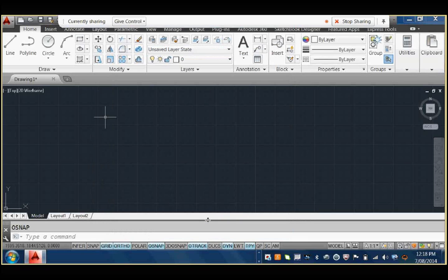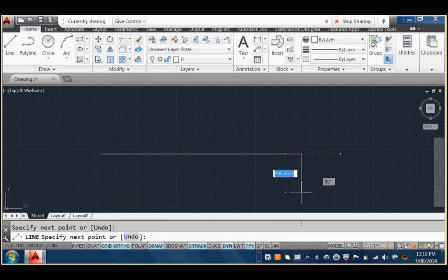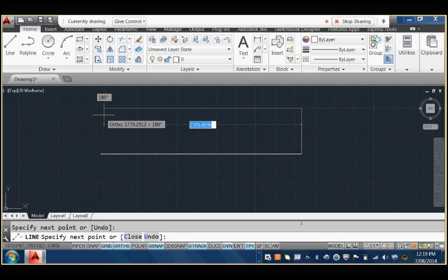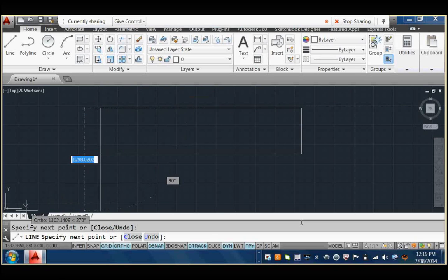Essentially, AutoCAD is command-based, and you can click on the icons here, or you can use keyboard shortcuts. So a line, go from here to here, and you can draw continuous lines. Object tracking, if I hover over an endpoint where that square is, it actually lets you know it's an endpoint, and move, I'll get that green line. So even though my cursor is around the midpoint of that line, there's another little X symbol, and if I click with a left click, it'll definitely line up with that endpoint. Okay.